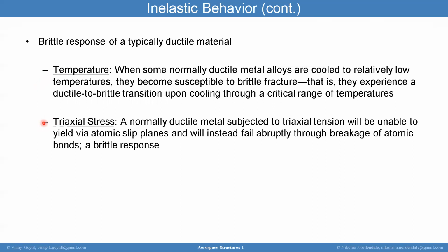Similarly, triaxial stress was one that was really elusive to me when I started practicing engineering, and it took a bit of a thought experiment to wrap my head around it. Think of triaxiality in terms of tension. If you envision a little block of material and try to pull it in tension in all three directions, if you can equally apply tension in all three directions, you're not allowing the atomic planes to slip past each other. And so it will fail due to an overloading of the atomic bonds, which is a brittle response.